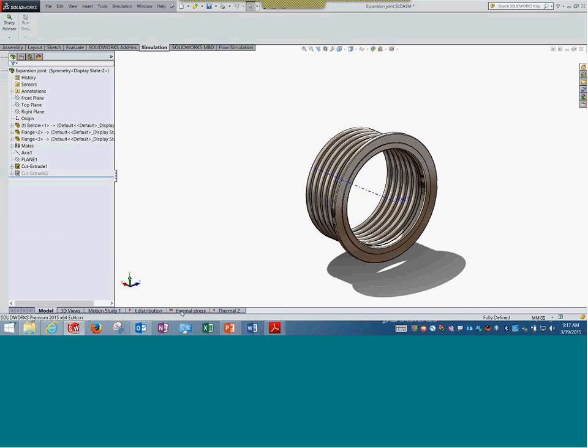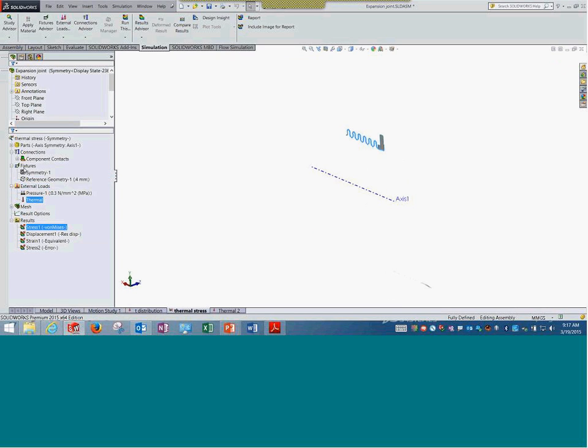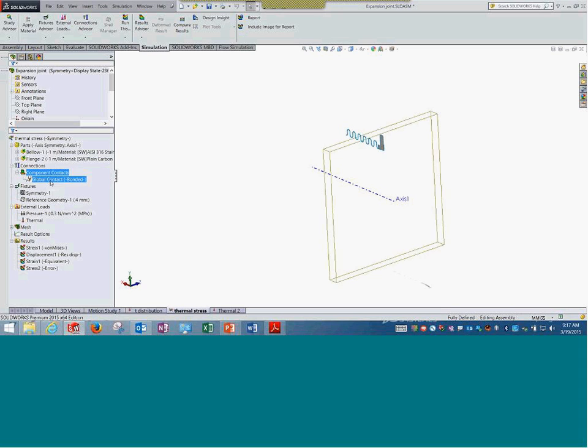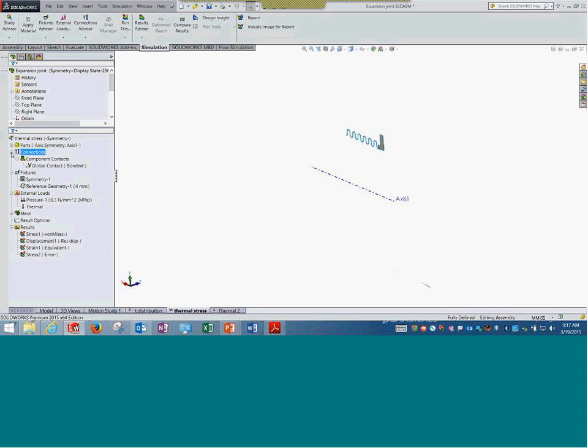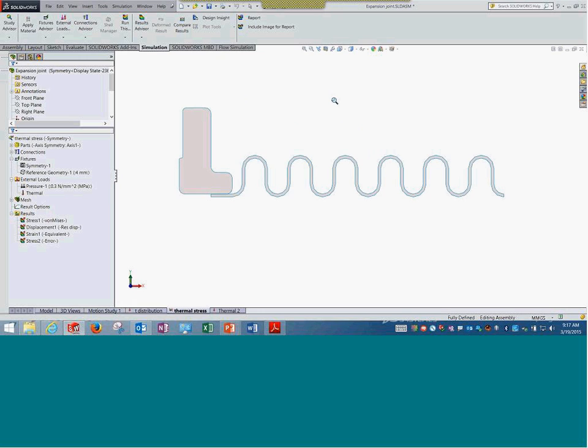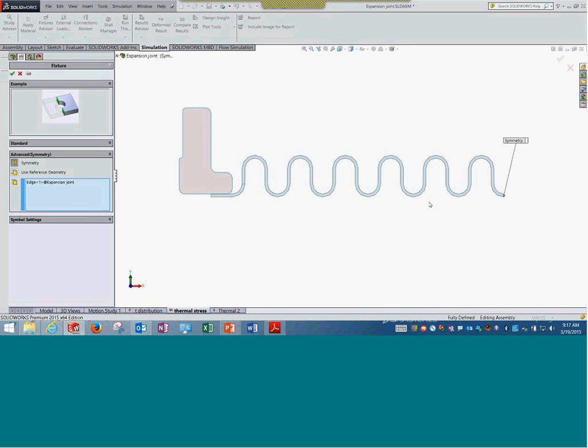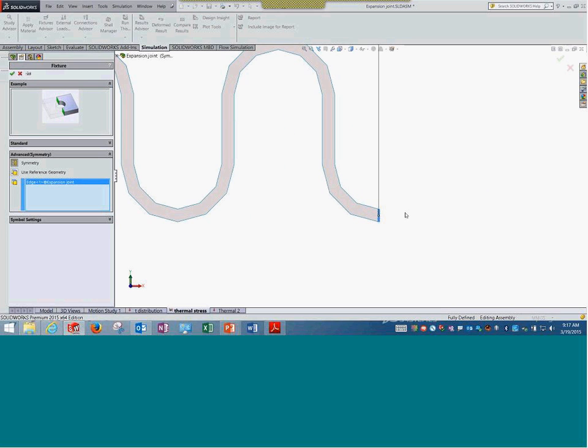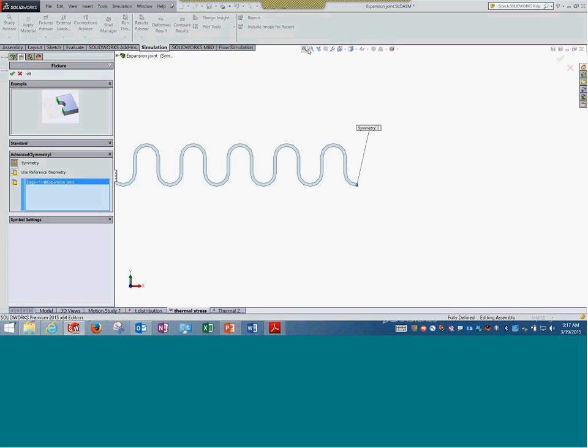Okay. Going back here, yes, let me do that. So this one bonded contact, this is fine. Now the other things would be what we want to understand. Let me take a standard view for this. Let's take the geometry to the screen so that I can visualize it correctly. Okay. So first is the symmetry boundary condition. At a certain end there could be two different things.